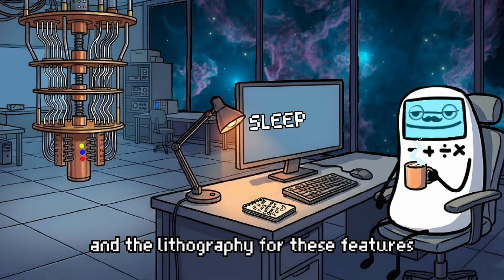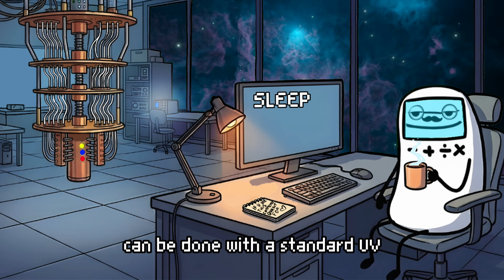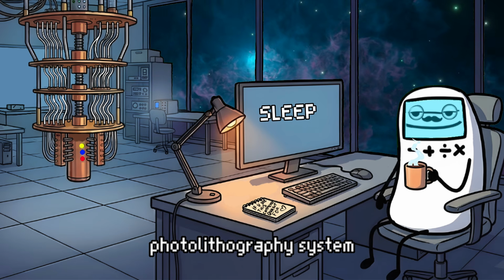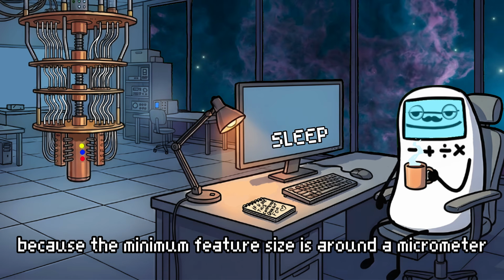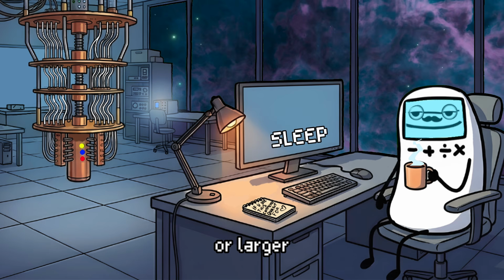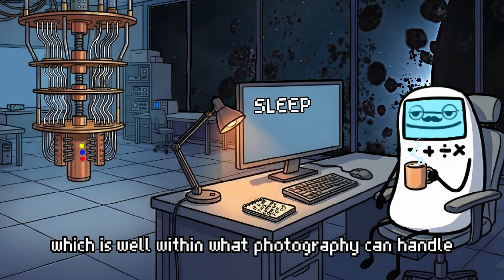And the lithography for these features can be done with a standard UV photolithography system because the minimum feature size is around a micrometer or larger, which is well within what photolithography can handle.